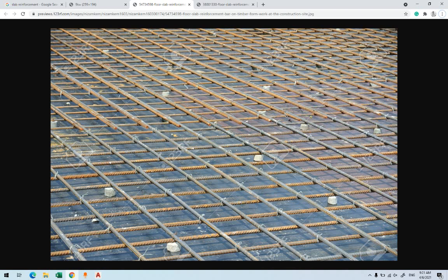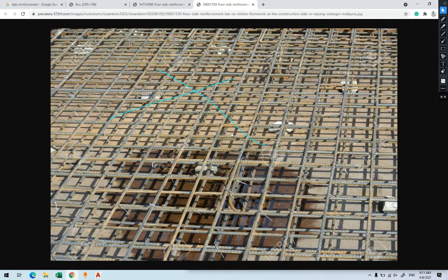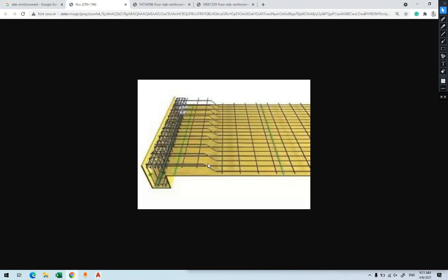So you have reinforcement in two directions. Well, you may have one layer, you may have two layers. Now, the two layers can be similar to the one in the foundation, or the two layers can be similar to a beam with bent bars. So you have a combination between slab and beam reinforcement. Two dimensions. You may have two layers the same way as the foundation we did, or you can have bent up bars inside it.